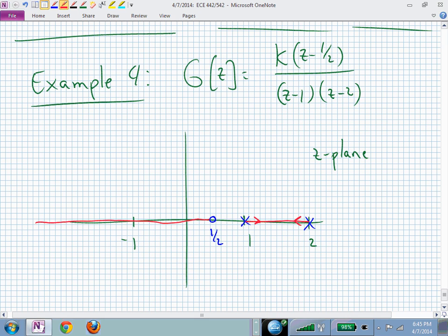Now, you can find the relative maximum here, and once you do, because of these 2 poles and 1 zero, the branches are going to form a circle centered on the zero. And the radius is going to be dependent on that breakaway point. Now you can just get out your compass, draw your circle, and there's your re-entry point.